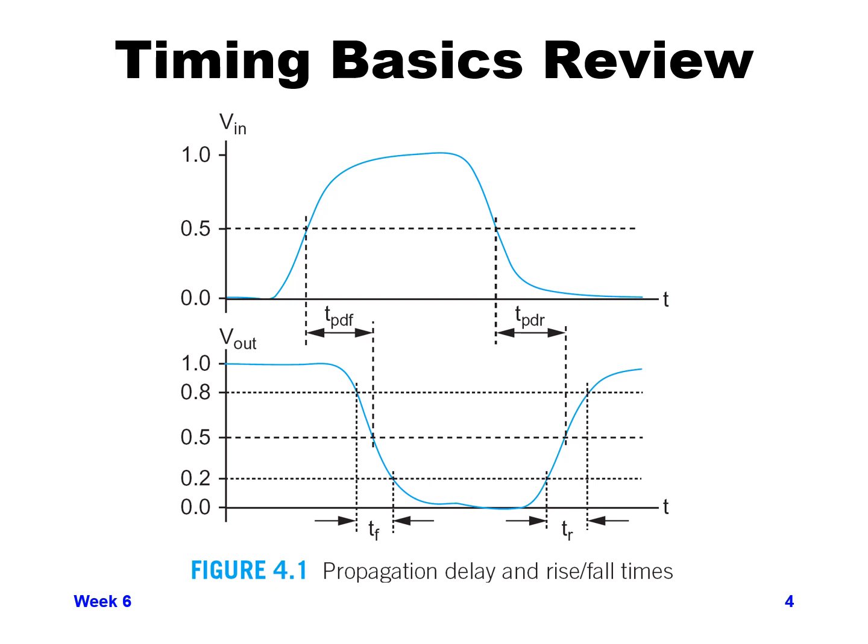When it crosses its 50% point, if we measure the 50% to 50% time, that will be our propagation delay, or T sub PD, and the F is for the output falling. So the propagation delay falling is the 50% time from the input rising to the output falling. The slope, the falling slope or fall time, T sub F, is the time that it takes the output to fall as it's coming from VCC down to the 80% value, 0.8.